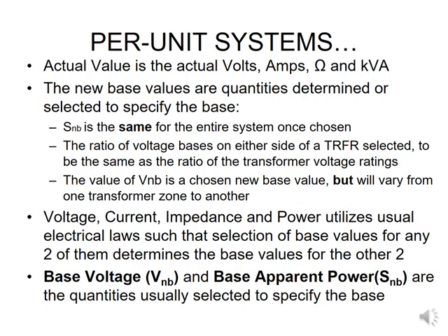But when I ask a question as the examiner, I may have just said to you, utilize 66 kV as your base voltage. So it's for you to then know that that base voltage might not necessarily be throughout my system, but it will change according to where I am in the system and what my transformer is telling me.